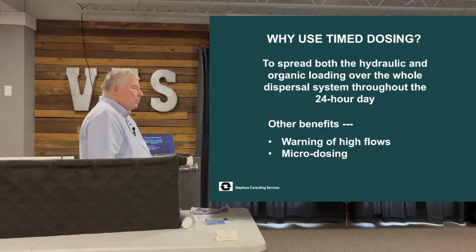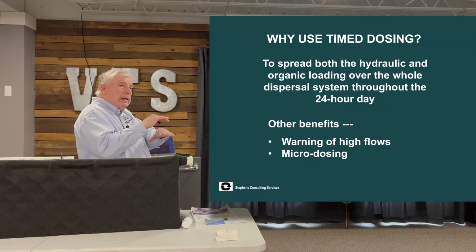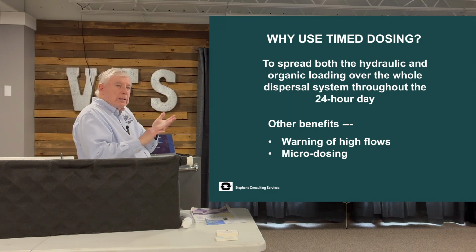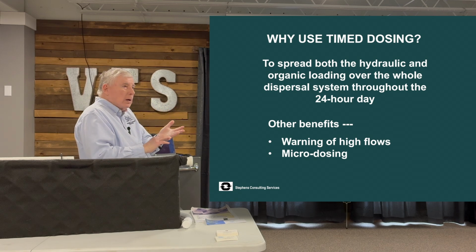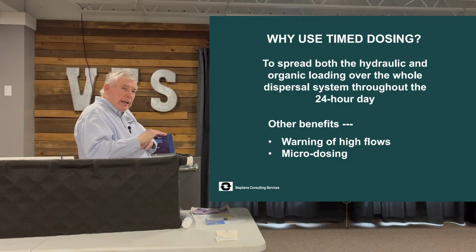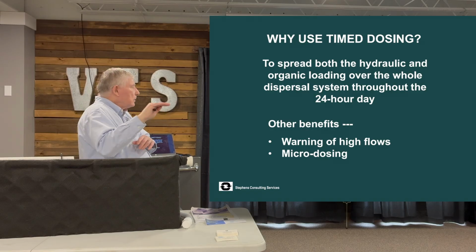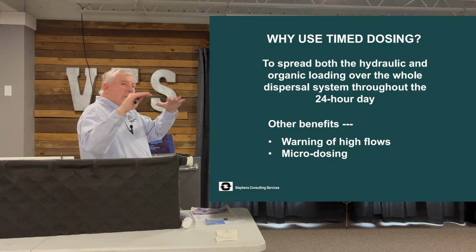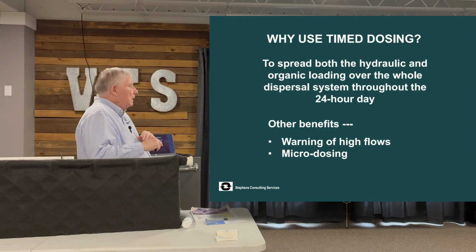So we spread both the hydraulic loading and the organic loading in the wastewater. You've got a dissolved organic food source in the wastewater, and you are spreading both that organic food source and the application out over as much of the 24-hour day as you can design for, over a longer period of time.